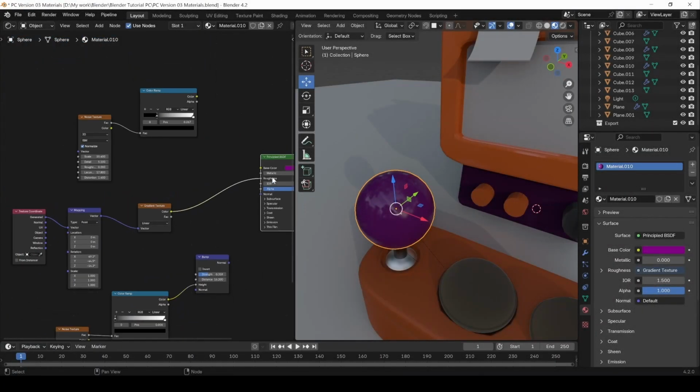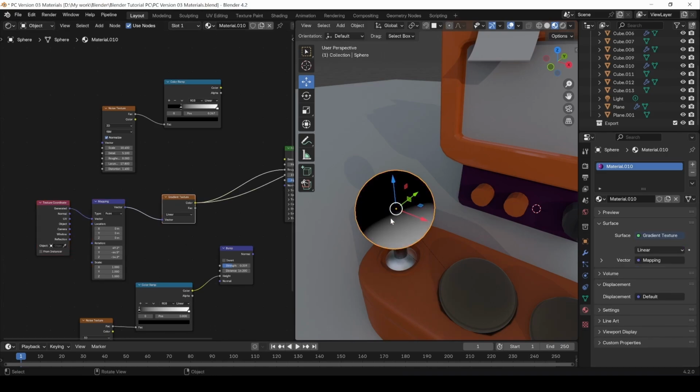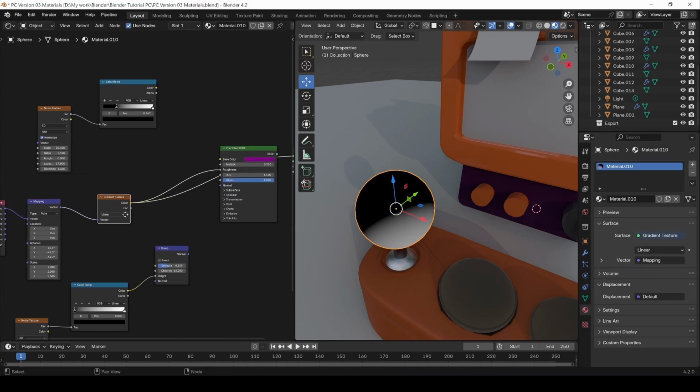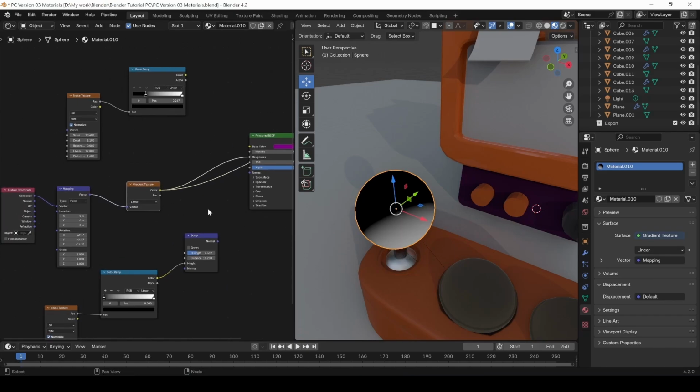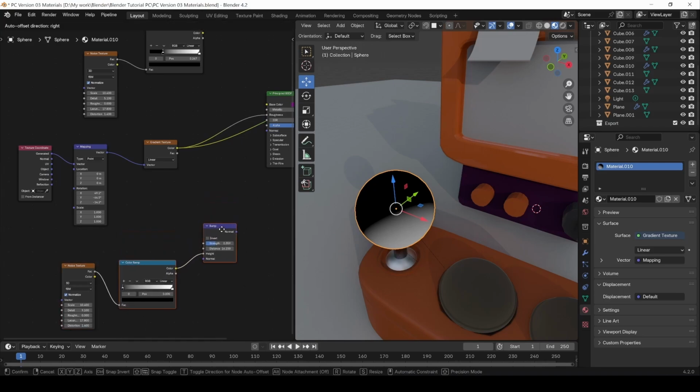And the way we did this, even though it looks like a simple thing, like we showed the UV where to put it, is actually creating a mask. What we did here is basically create a mask. We said that this part should not be reflective, but this part should be reflective. And if we use mix nodes, we can actually mix nodes that will be appearing only on the white area or only on the black area.